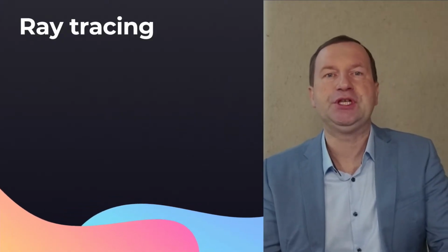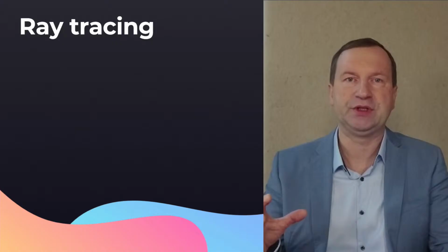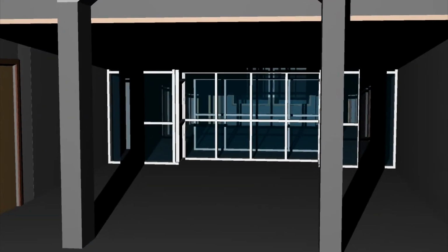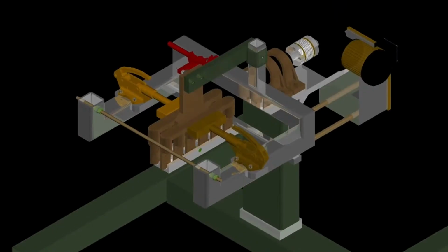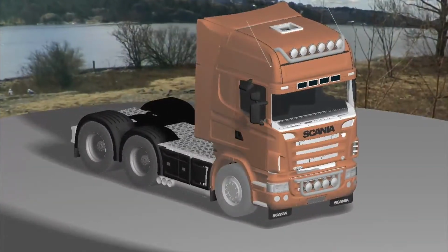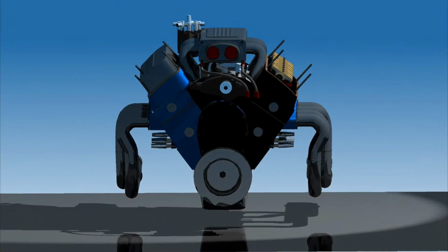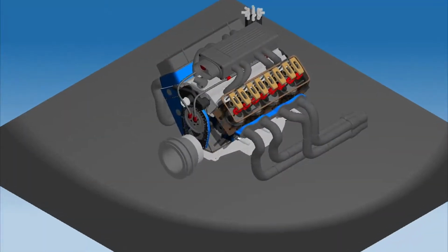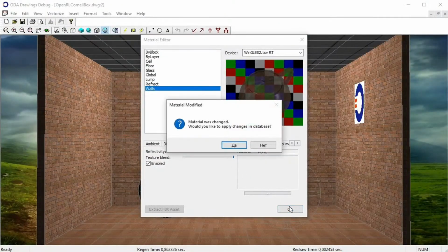This year, we have continued developing ray tracing functionality as part of our focus on improving rendering quality. Ray tracing enables the visualization of photorealistic images with various real-world material effects. It's widely used in products that require final, high-quality rendering, as ray tracing techniques involve intensive calculations. Primarily, finding intersections between emitted rays and scene geometry and calculating material properties on surfaces. This process usually requires substantial rendering time.